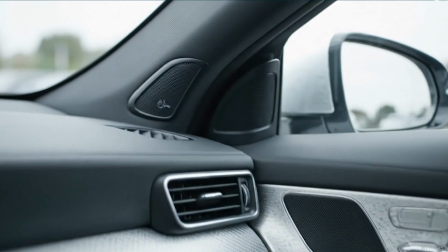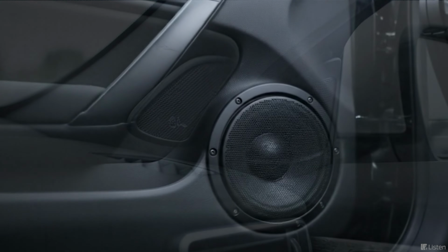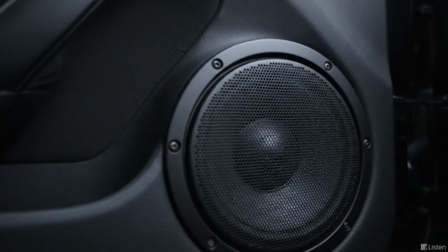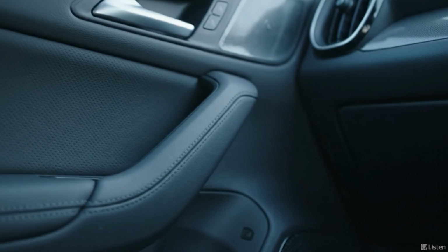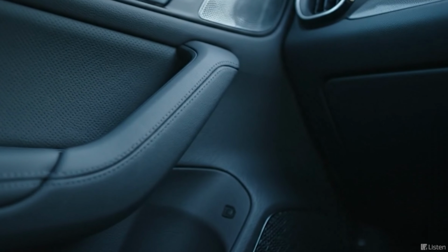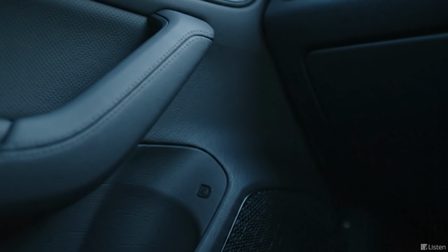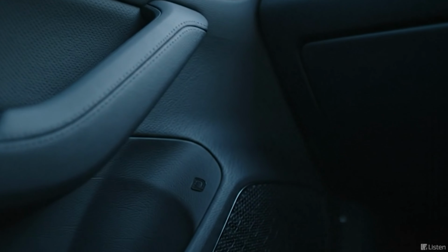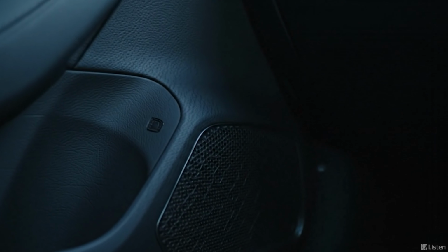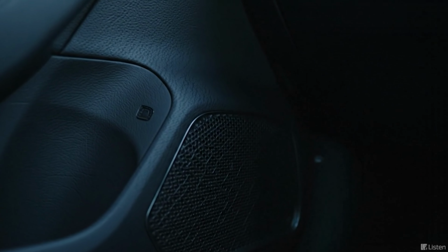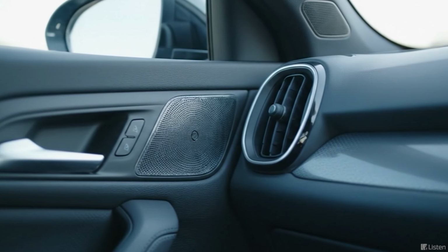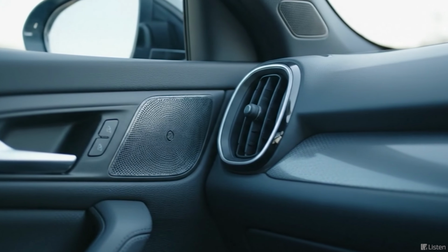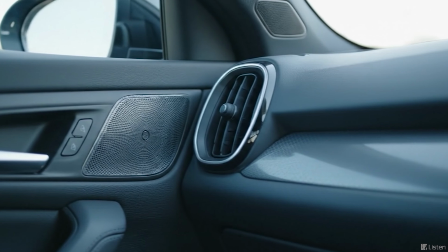It detects any audible buzz, squeak, and rattle that may be caused by the speakers vibrating the door panels, loose wire harnesses, etc. These noises degrade the listener experience, so it's important to assess the vehicle thoroughly. It's actually a good idea to make these measurements before you make the system characterization measurements, as this ensures that the infotainment system is properly installed in the vehicle under test. You can also use this test as an end-of-line check to verify vehicle integrity.